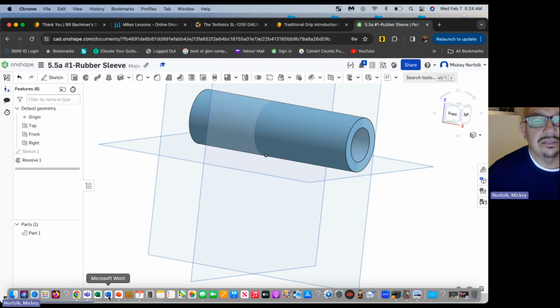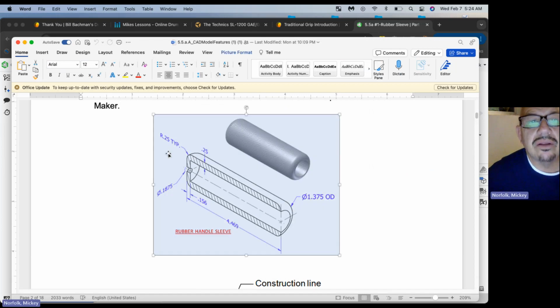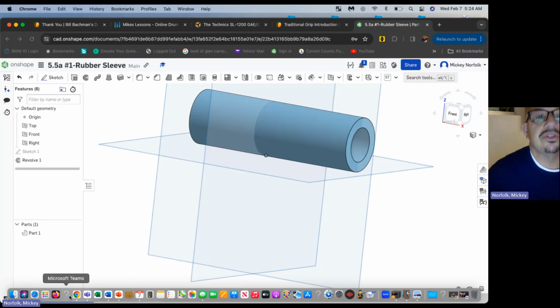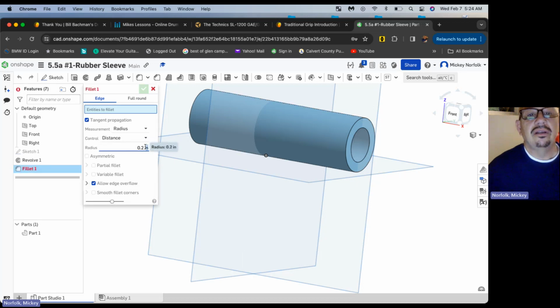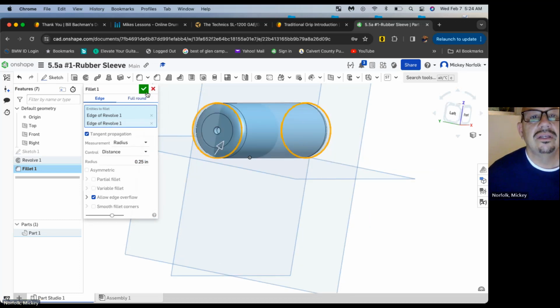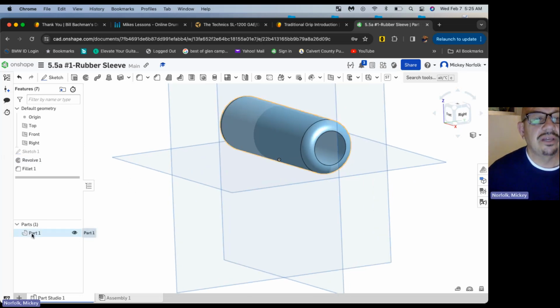If you look over here, it is rounded at the ends, and that rounded radius 0.25 typical is referring to the fillet. So we're just going to hit fillet because that gives us a nice rounded feature. Make sure that your radius is what it told us. So if you just select it and put in 0.25, it automatically knows it's inches. Left click the outside circle there, outside circle here. Do that. You are done with shape one, except you got to make it a color.